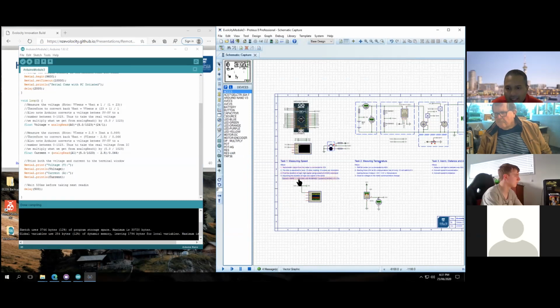Right, now we are going to basically go and use the input from this tachometer. And first, what we are going to do is we are going to read how long this, so I'll draw this here. Yes, we said that we have a pulse like this. And we want to first work out how long this pulse is high for, okay? Let's say T here. So I'm going to write some Arduino code to do this now.